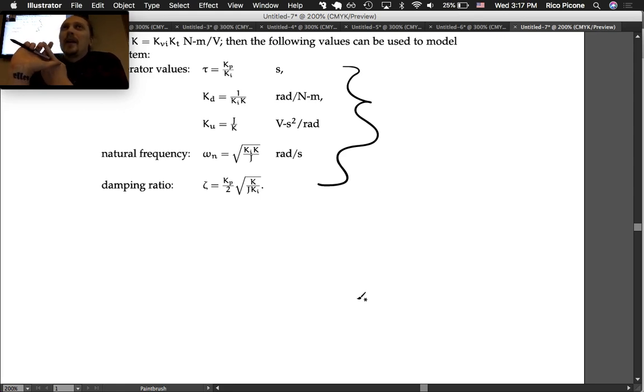And bearings are fairly well approximated as linear dampers, so damping comes in through them, and then also the external bearings. So those two places friction comes in approximately as damping. And there are other losses in the system too, and those are electronic losses, like the heat that's generated through the coil, the windings in the motor.